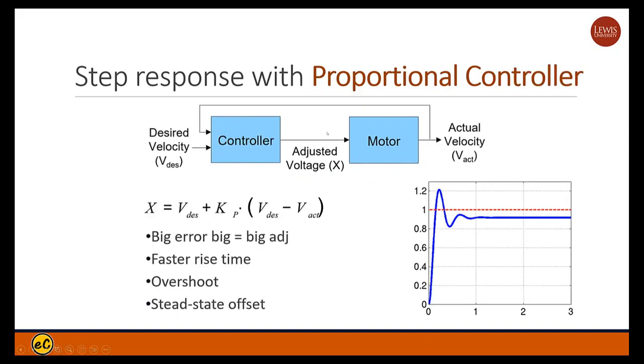The next one is the proportional controller. That means you use the difference between your actual speed and your desired speed, and use a K amplifier to amplify it. But the problem with a pure proportional controller is that there's always a dead zone, and you can never catch up to the real expected speed, because of a systematic difference.